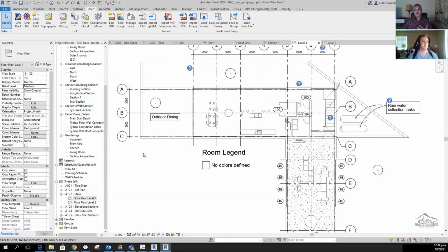So that's why when you use Revit, you have to be aware of what's going on, and you have to understand the software very well, because it is an interactive software versus AutoCAD. AutoCAD, especially AutoCAD 2D, is a static software. If you move this door, it will move a little bit and the wall will remain open. But with Revit, if you move it, the wall will close.